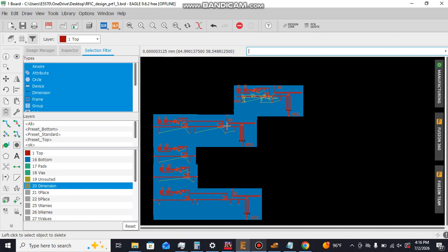to be able to maybe get a better result for my IF output of 100 megahertz, because it may not have enough signal coming through, and it wouldn't be enough to get to the output probably. So I need to get enough gain into my mixer here.